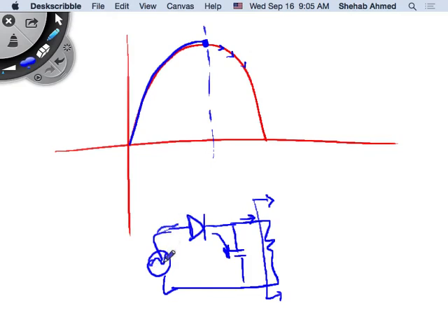If my input source voltage starts going down, and my capacitor voltage is maintained because I'm not drawing any current out of that capacitor, then what happens to this diode is that it blocks. Right? So if this diode starts blocking, then I have a circuit that looks exactly like this. Just the capacitor. Capacitor feeding nothing. Right? Its voltage will never change for an ideal capacitor. Will this voltage ever change?